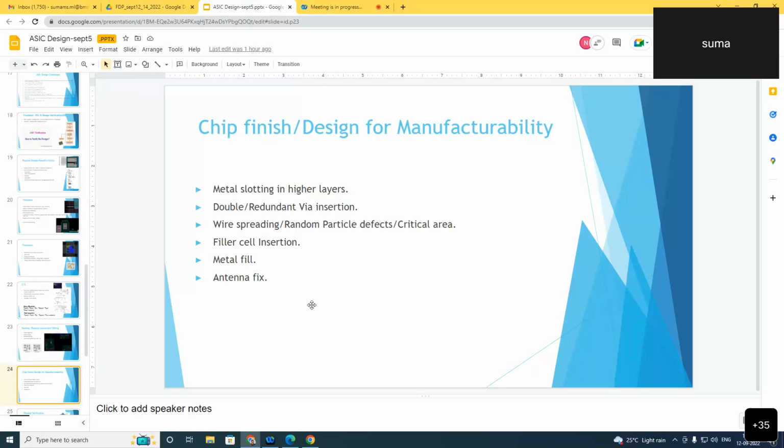So we need to fill the design while minimizing the capacitive coupling. The foundries also respond with increasingly sophisticated requirements to achieve the required fill density. So metal fill is also a concern, and of course antenna fix will come into the analog. I will not touch upon that.